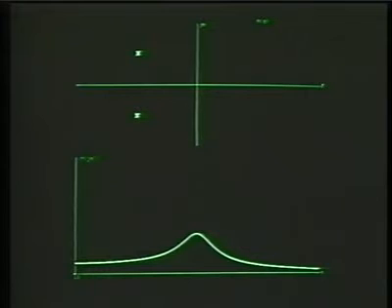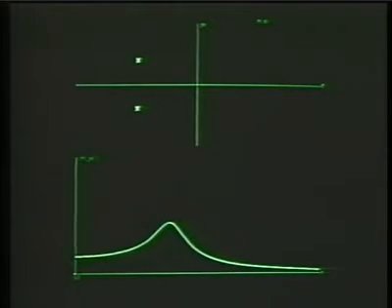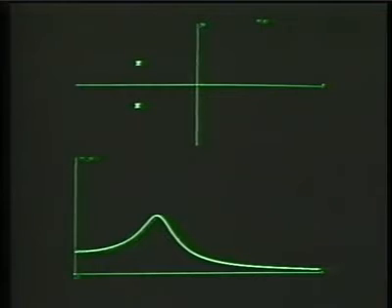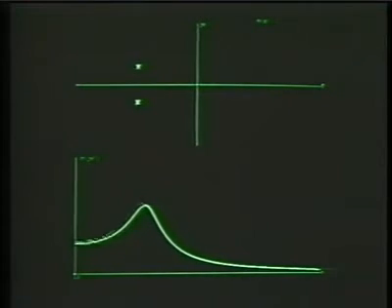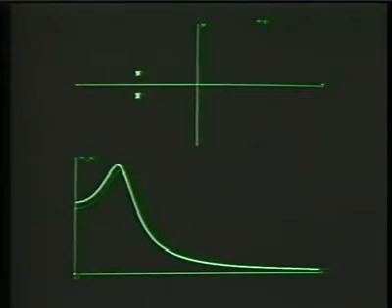And also in the process, incidentally, the height of the resonant peak will increase because, of course, the lengths of the pole vectors are getting shorter. And so we see now the resonance shifting down toward lower and lower frequency.